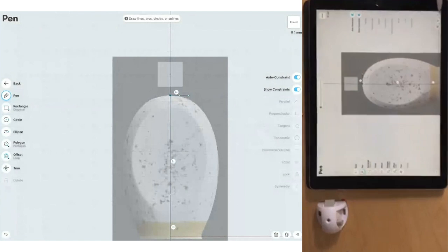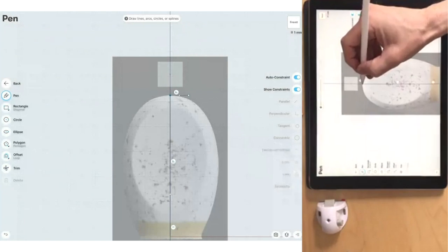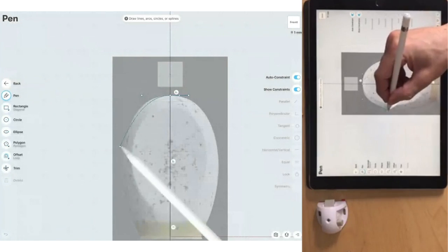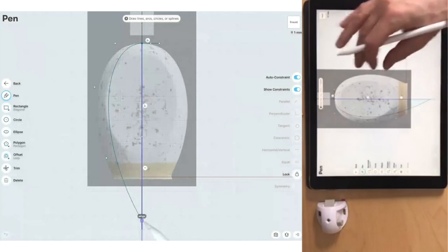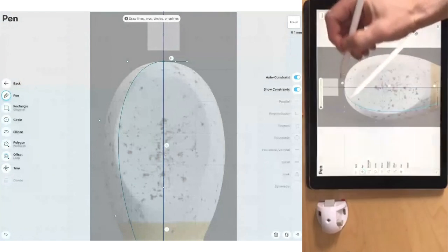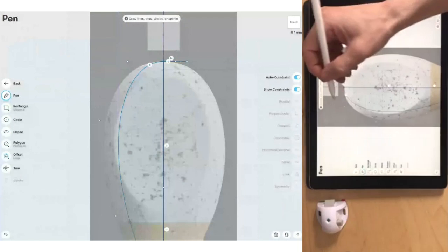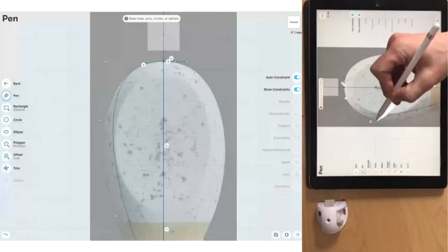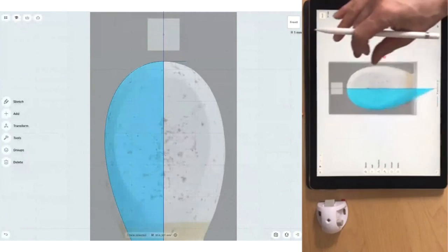So it's horizontal. And it's up to you now if you want to use the fit point or the control point. I will actually show you the advantage of both. I will use the control point first. So from here, I start drawing and I press and press and press and maybe stop. I need to figure out how many points I really need. Also here, the trick is make this as simple as possible. Less is more. The curve we make tangent to that line. So at this point, I can't move up and down. I can only move it left and right. That actually makes sure that once we revolve this shape, the top won't look pinchy.